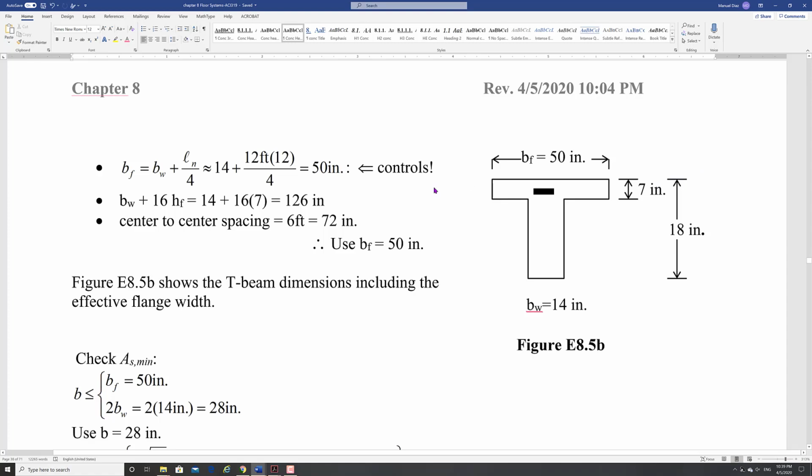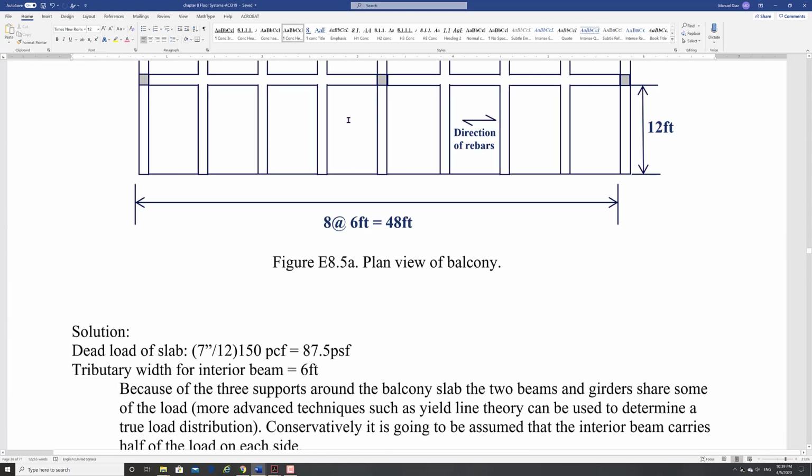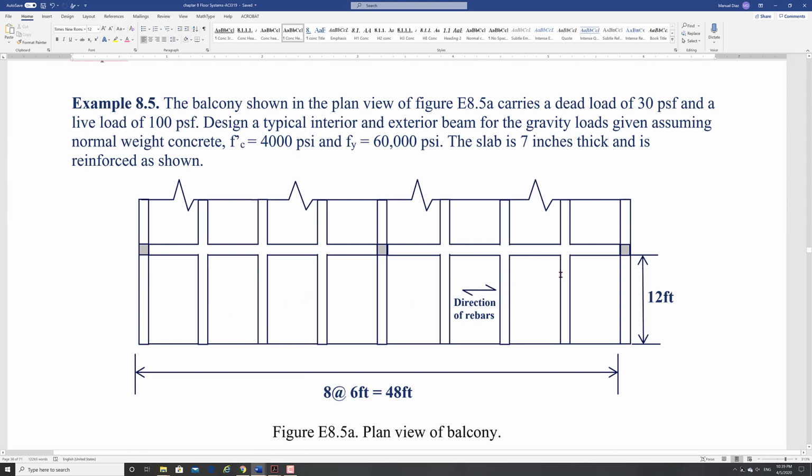right? So we go back here, right? You have bars going this way on this slab, right? You also have bars going this way in this slab, right? Which bars are these? Yes, temperature and shrinkage bars. Okay, so you have cover, the bar of the slab, and the shrinkage bars. And then you have to put your bars for the beams. So you're not going to put it right there, the same location, right? And so the 1.5 that we normally use will not be enough.